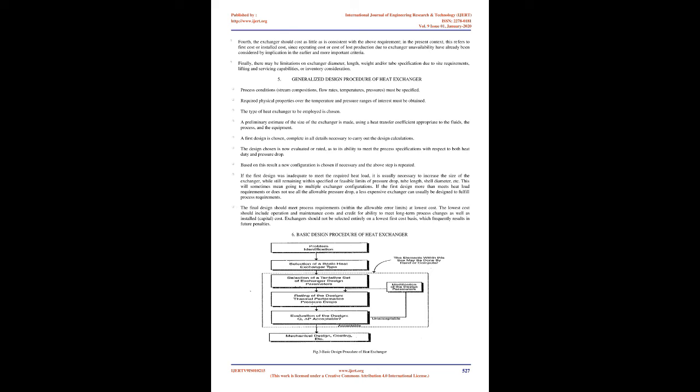For comparison, the same maldistributions are handled with the parabolic and hyperbolic dispersion model with fitted values for the axial dispersion coefficient and third sound wave velocity. The analytical results clearly demonstrate that the hyperbolic model is better suited to describe the steady-state axial temperature profiles.